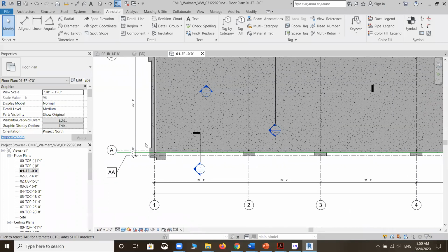So now, the curtain wall system is a type of architectural component. For the past several weeks, we have been working on structural systems. We all understand if you want to model structural systems, it's always going to be modeling from its top to its bottom. In this case, we're modeling an architectural component. So this time we're going to model from the bottom of the curtain wall to the top of it, right? So the bottom of the curtain wall is finished floor.